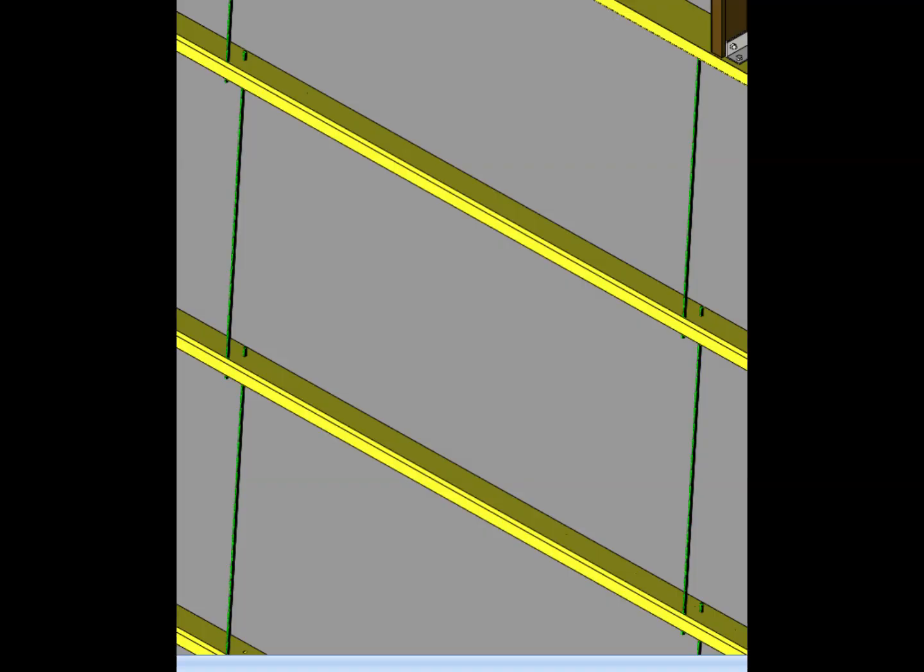This is also why simply recognizing a sag rod from a 2D drawing is not enough for practical detailing. A detailer should be able to move from the 2D framing drawing to the 3D model, identify the same member, and then understand its physical position within the structure. In this model, the close-up view makes that transition much easier. Notice how the sag rod continues between the horizontal framing levels. The same type of arrangement can be repeated at other locations depending on the structural framing requirements shown in the project drawings.